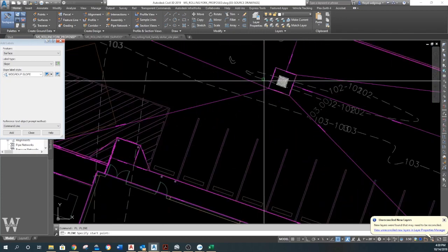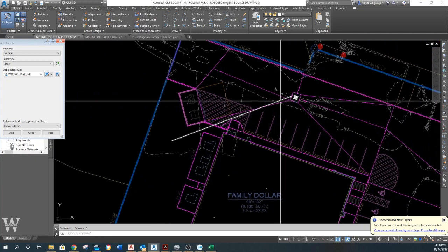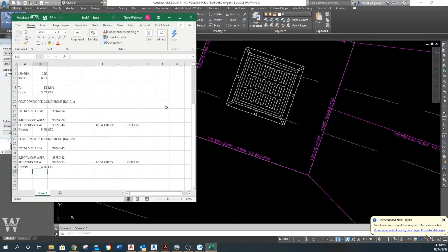Okay, so I need to be able to come from right here, somewhere along in here, and put a pipe that, if I put 2 foot of cover, and if I do 102.805, so I'll go over here, if I do 102.805, and I'm minus 2 foot, this equals 2 foot of cover and a foot of pipe, then I've got 3, and that equals that number minus that number. I need to be at 99.8 at least for the bottom of my pond, because that gives me 2 foot of cover and a foot of pipe.